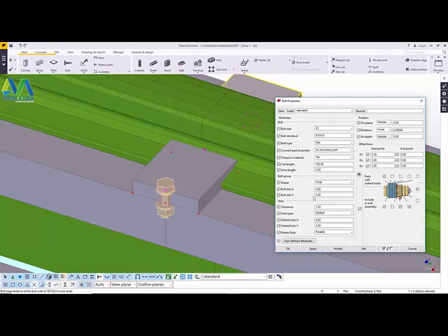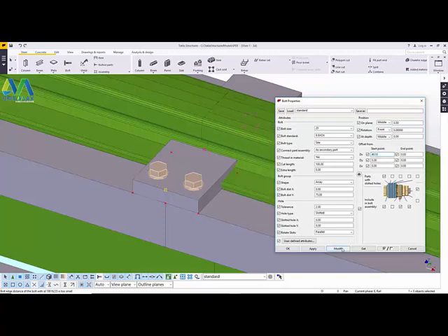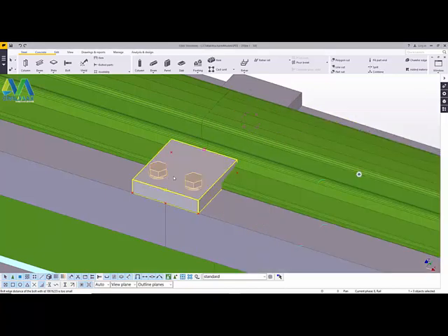And to do that, we'll just come to group, bolt group, and I need just 100 or 75 here, 75, and click apply, and still off the mark. And to bring it inside, I'll come to this spot and feed 40 and see whether it will move inside. It has gone inside perfectly, and that is the position we wanted the two bolts to sit on. I'll click apply and click accept, and the bolts have been selected.